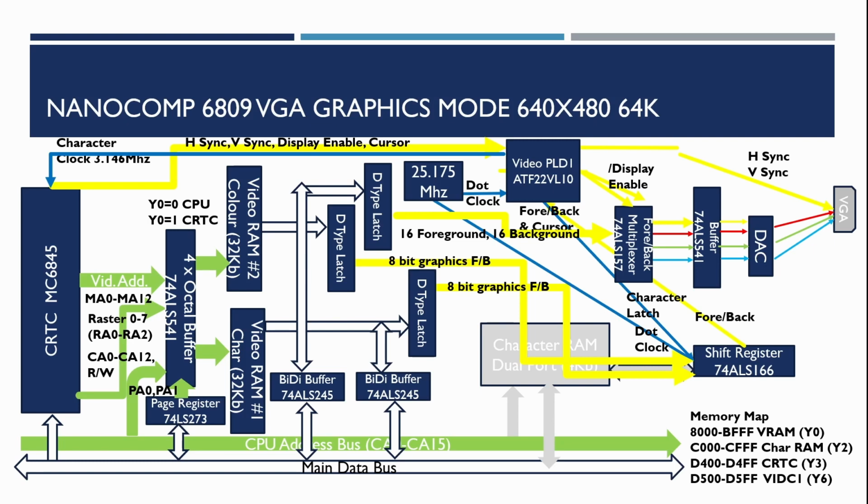So the PLD programming rules were quite complicated, but now that it's all working, it's all fairly straightforward, but it took a little while longer than I thought it would to get all this working properly. So what this does is that the bit values coming out of the video RAM determine if it's a 1, then it shows the foreground colour, if it's a 0, it shows the background colour, and what we're also doing now is adding control signals to the original colour latch here so we can address it via the CPU and determine what the foreground and background colours will be.